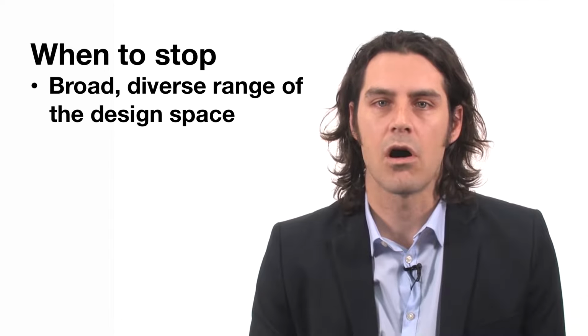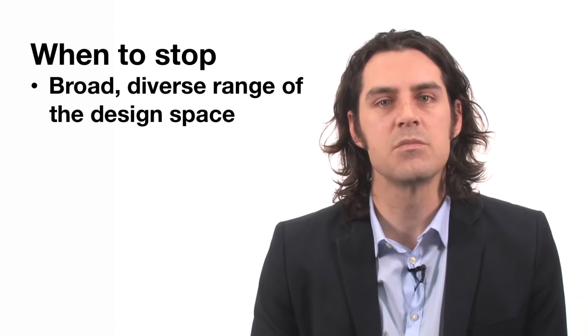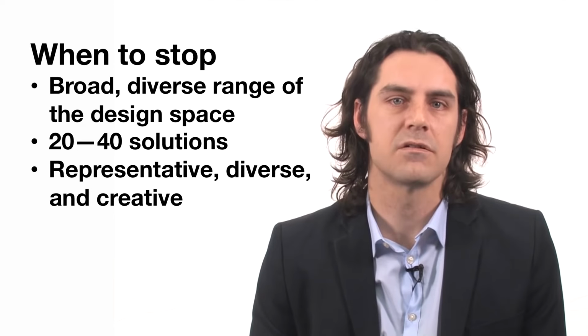Students often struggle with when to stop generating solutions using their Morph charts. Your goal should be to generate enough solutions to get a broad and diverse range of the design space itself. And often this means 20 to 40 solutions which are representative, diverse, and creative. Morph charts give you no information on the utility of the solution. By that we mean that there's no evaluation or ranking which would allow you to select the best solution.